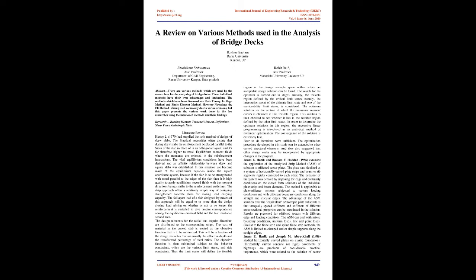The method is applicable to plate stiffener systems subjected to various loading conditions and with different boundary conditions along the straight and circular edges. The advantage of the ASM solution over the equivalent orthotropic plate substitute is that unequally spaced stiffeners and stiffeners of different cross-sectional properties can be introduced in the solution. Results are presented for stiffened sectors with different edge and loading conditions.